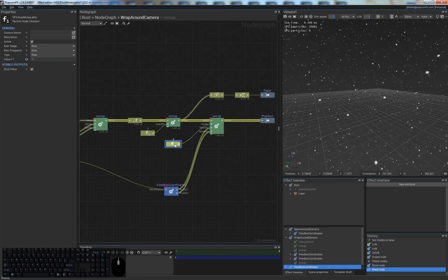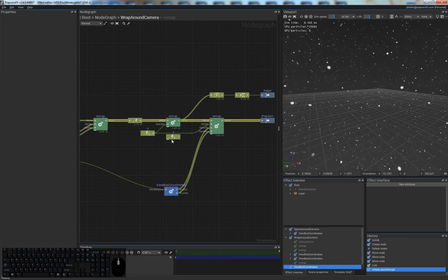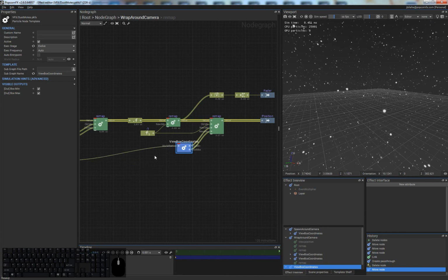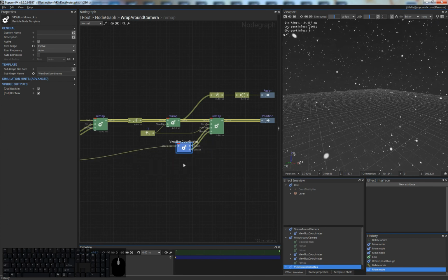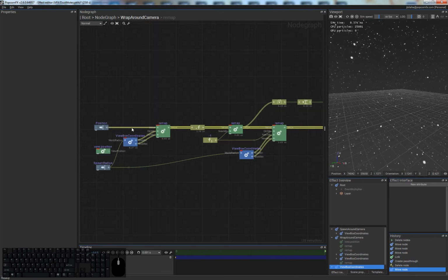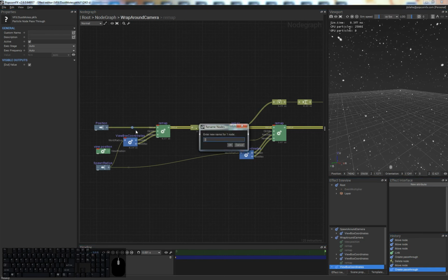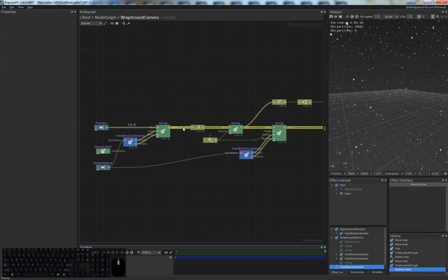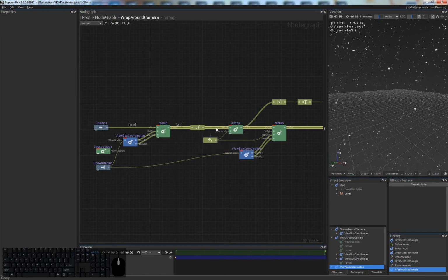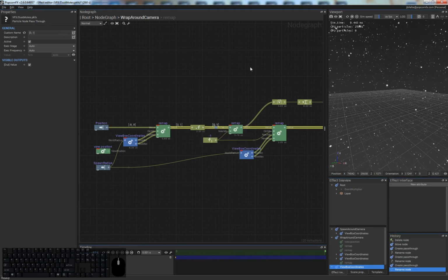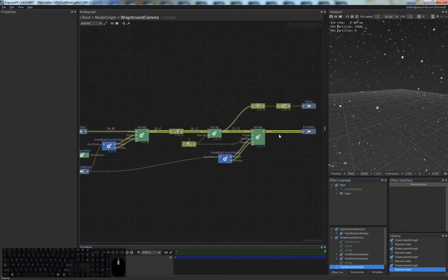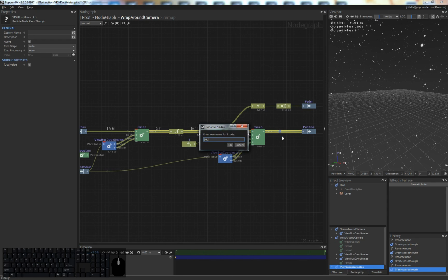And I will actually reuse that node as well. So you can use Alt Shift to create a pass-through node, and it magnetizes the closest wire it finds. Right, so just for things to be clearer, I will add a bunch of additional pass-through nodes that I will just rename with the range of the values. So here it's -world radius. Here it's 0, 1. Here it's still 0, 1. Here it's -1, 1. And here we remapped it back to -world radius, world radius.